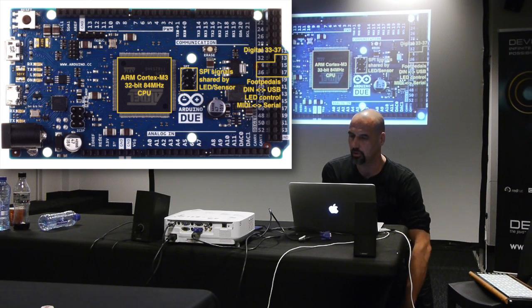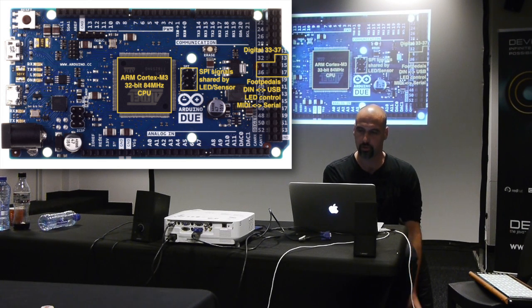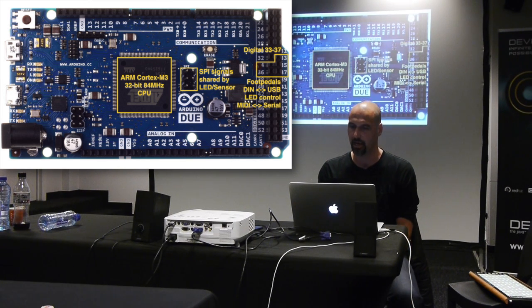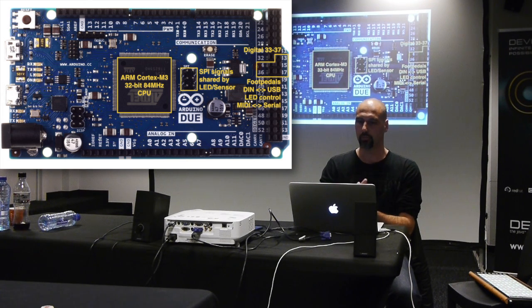And so here summarized, you can see that it's using only a fraction of the digital pins that are available through the Arduino, so the pins 33 to 37, and it's doing quite a lot over the serial peripheral interface, so the SPI interface, and it's using the slave select mechanism in the Arduino Due to actually select different peripherals that will get or be sent serial information based on what you need.